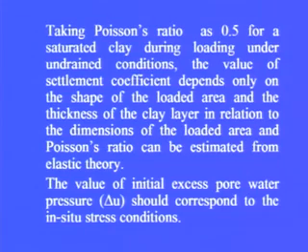Taking Poisson's ratio as 0.5 for a saturated clay during loading under undrained conditions, the value of settlement coefficient depends only on the shape of the loaded area and the thickness of clay layer in relation to the dimensions of the loaded area, and Poisson's ratio can be estimated from elastic theory. The value of initial excess pore water pressure delta U should correspond to the stress conditions.